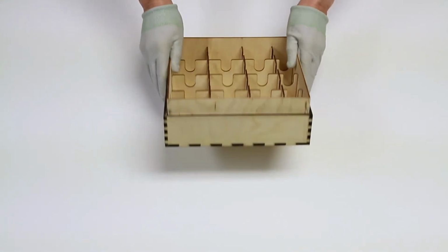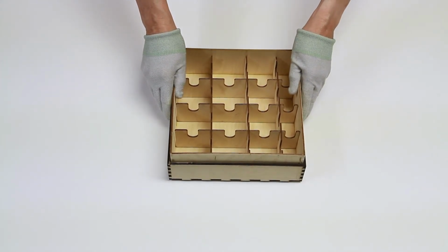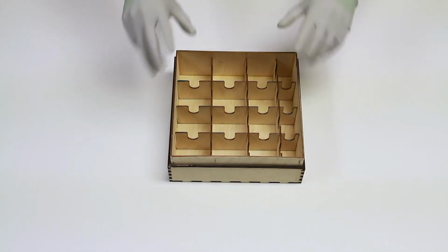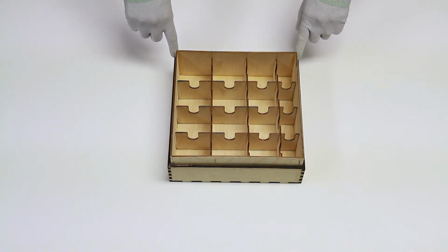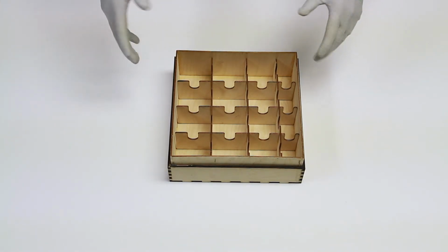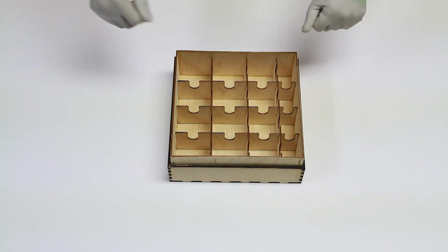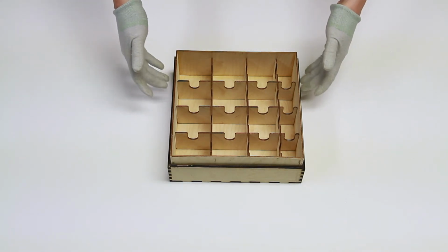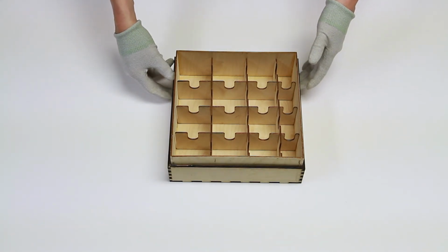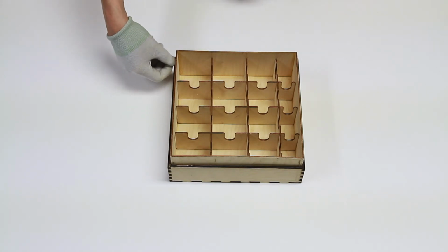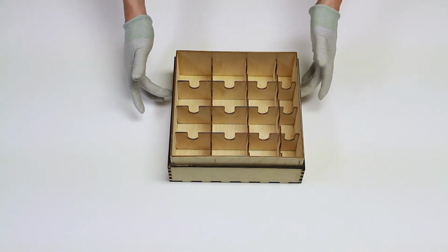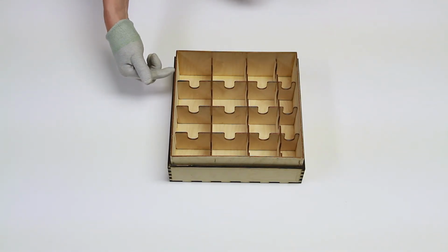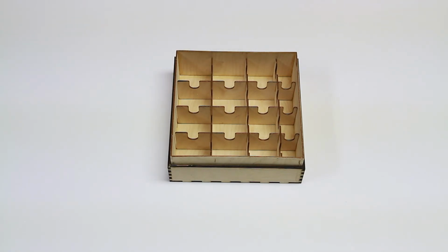So here you can see how the liner fits into this other material that's about 0.2 inches. It's important to measure because plywood labeled 1/4 inch can vary from 0.2 to almost 0.3 inches depending on how you get it. Then this was the base. Well, we made the base height, controlled it by the inside dimensions to not be all the way to the top. Well, we did another exactly the same base but a different height so that it would come down to this edge. And that became the top of the pillow box.